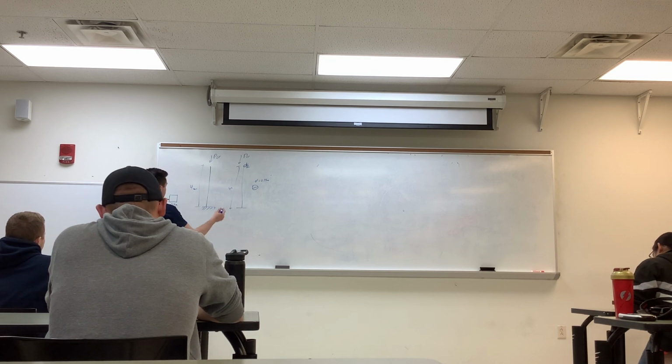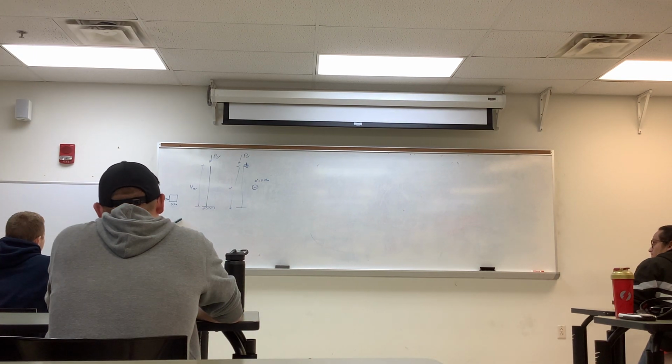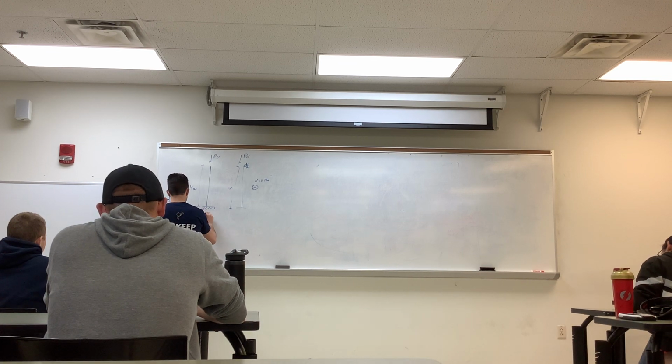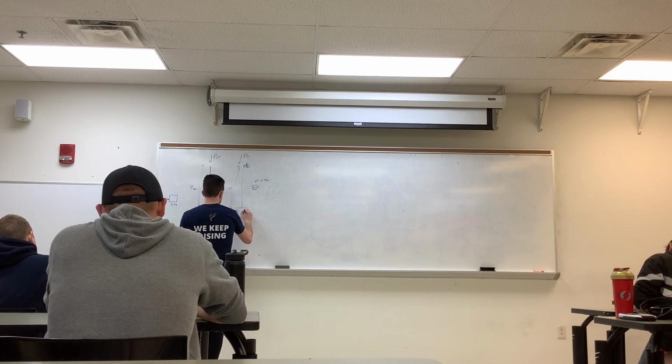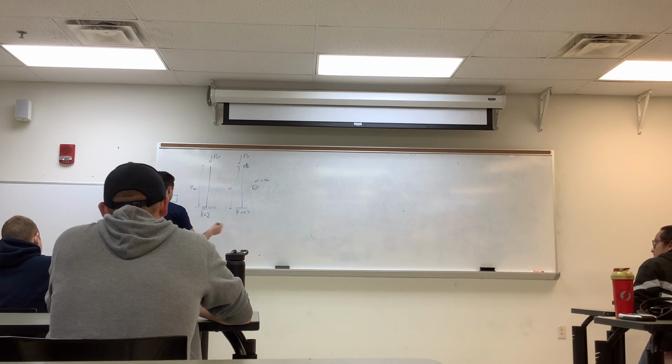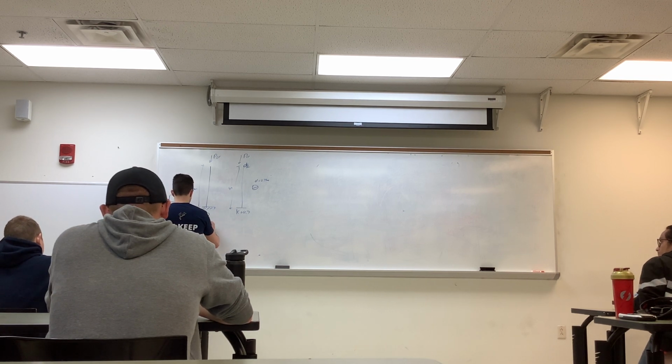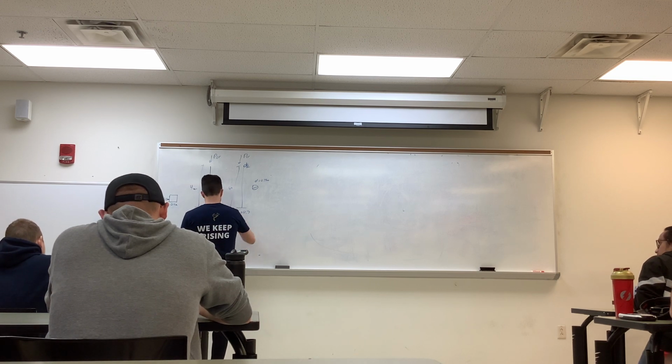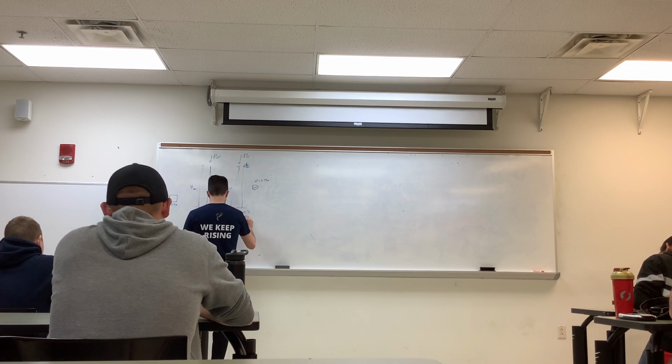I'll give you guys the K values for each on the file. There are different kinds of columns with regard to fixed, free, pin, and so on. For fixed free, K is equal to 2. For fixed pin, K is equal to approximately 0.7. It was like 0.699 or something like that, so 0.7 works here. When we calculate this out, our effective length for each one is just KL.